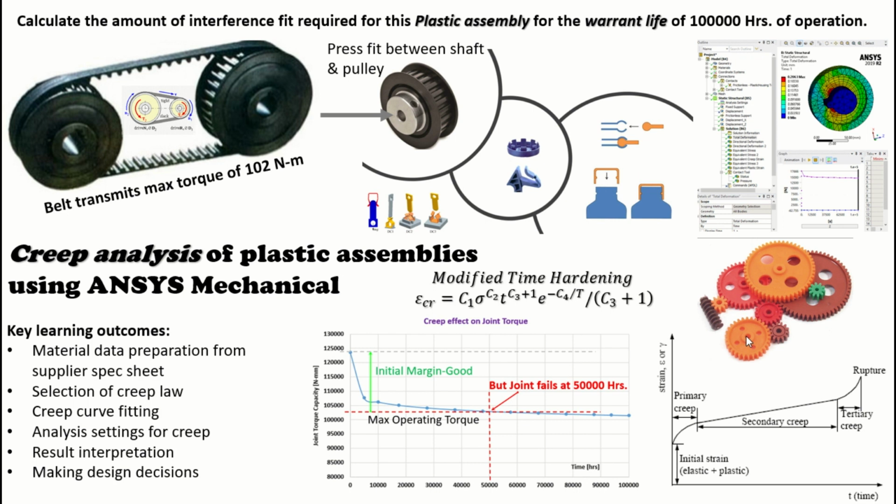We need to really simplify the model to an extent where the numerical computation becomes relatively simple, but care should be taken that the simplification we are making does not compromise anything on the physics of the problem. Thinking about applying a friction coefficient in this contact and applying a torque as an external load and seeing how the stress or strain develops in the model, yes, can be done.